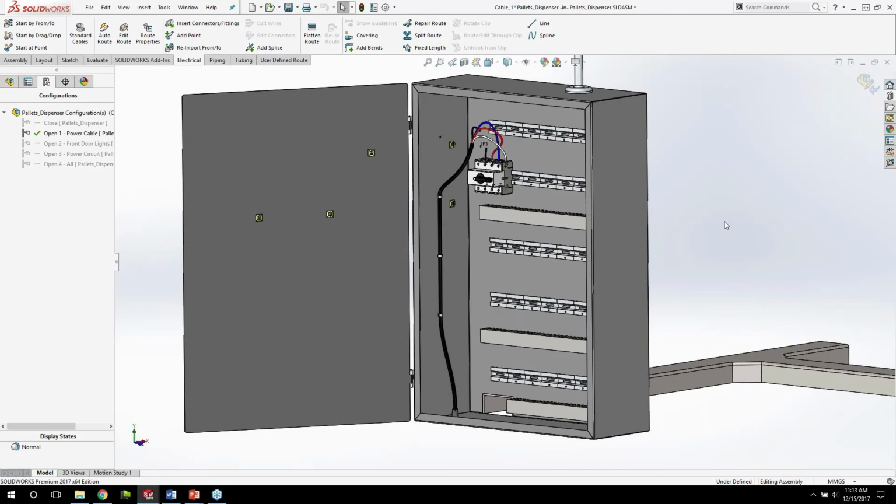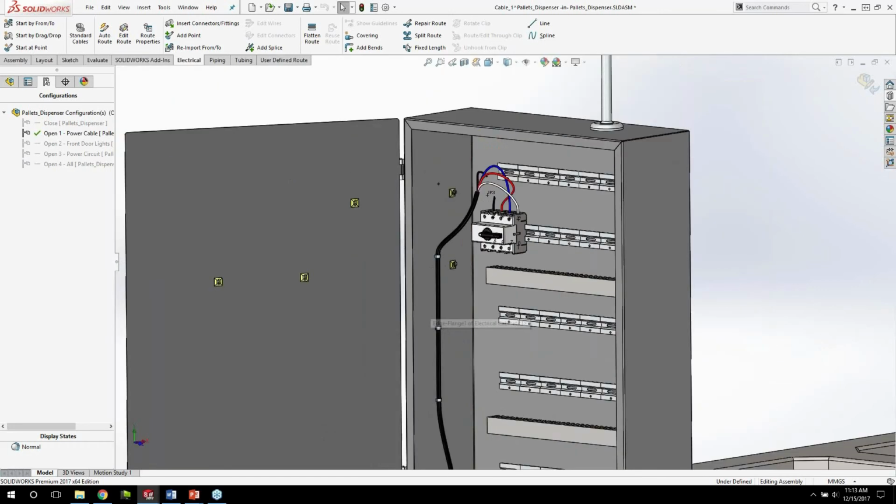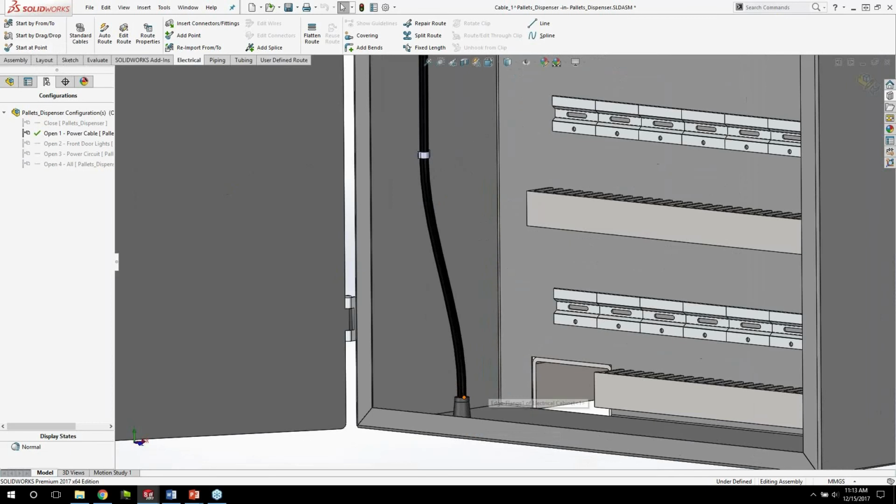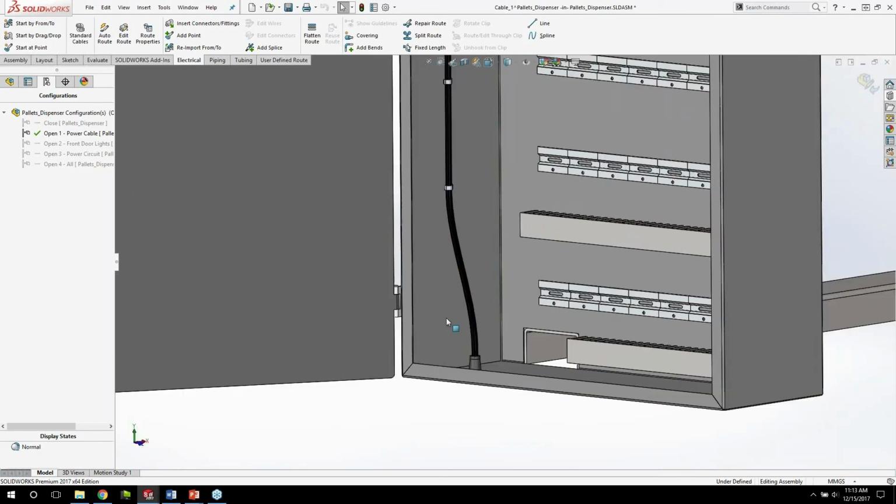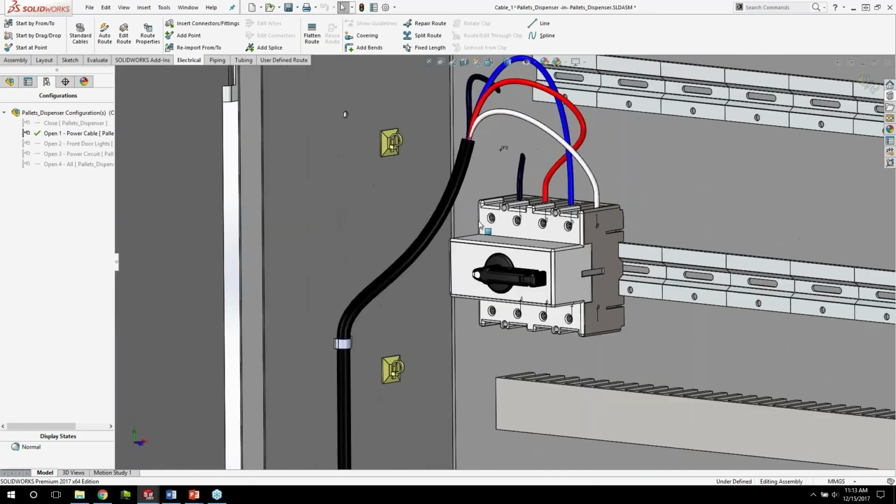Right. So just like that, I created this power cable here. Again, starting with a point. So those C points, those route points, can get created on these components and then added to the route like I did here manually, and then go ahead and create this here.